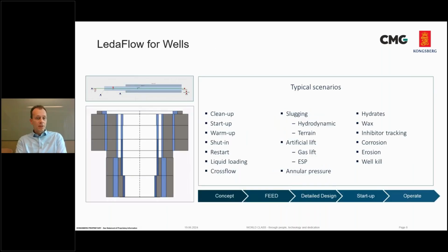Then LedaFlow for wells. So this shows some of the typical scenarios that you can simulate using LedaFlow. In LedaFlow, you can build a quite detailed well model, modeling not only the flow inside the tubing, but also flow inside multiple annular spaces around the tubing.